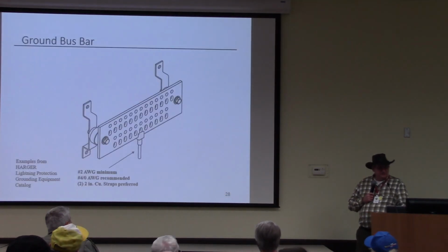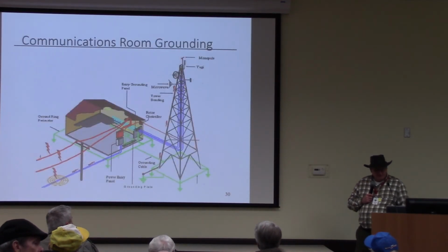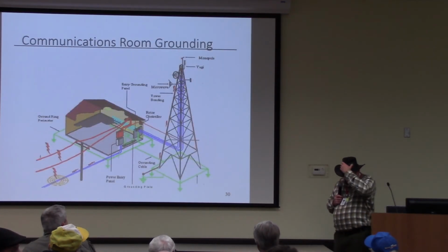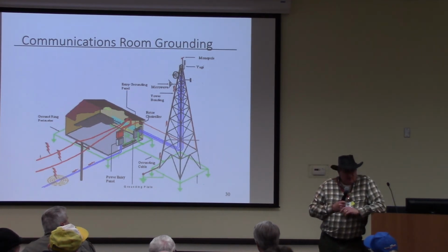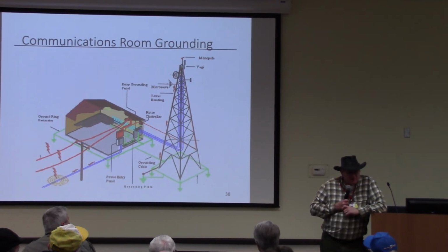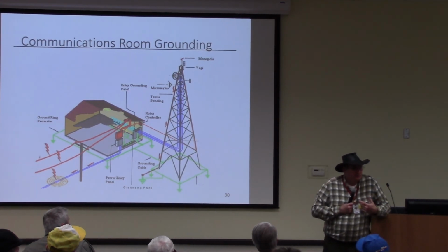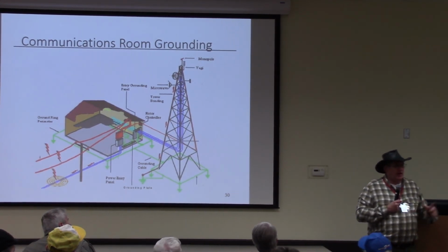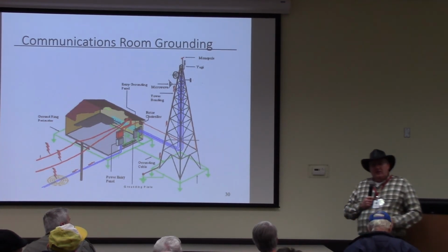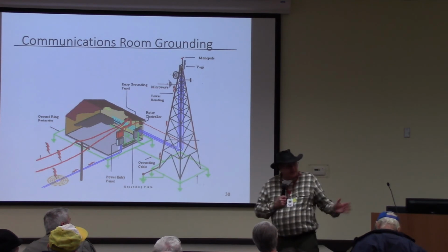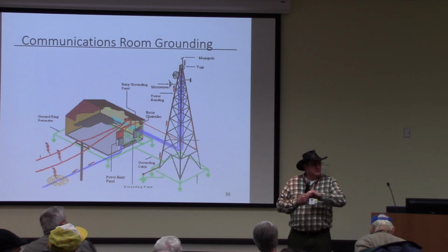Question. Yes. How long a distance would you say that situation would apply where your service mains are as close to your entry to your shack? 10 feet, 5 feet, 20 feet? I'd say if they're within 15 feet of each other, and if it was me, if they were 15 to 16 feet apart, I would just run the wire in between 2 ground rods, and you'd be done. If you start getting less than that 16 feet, then the only thing I would do is increase your number of ground rods at that point.